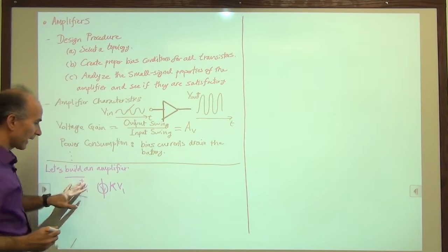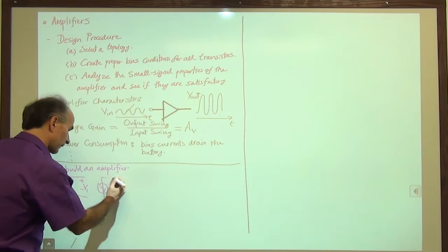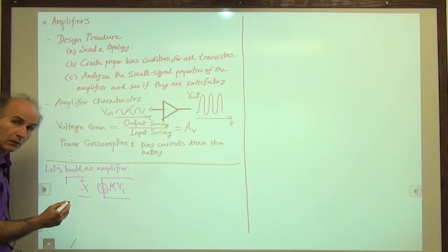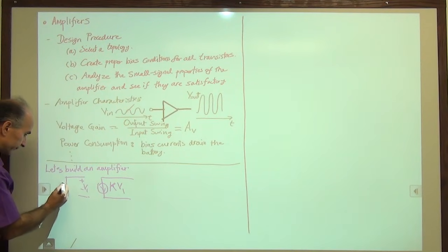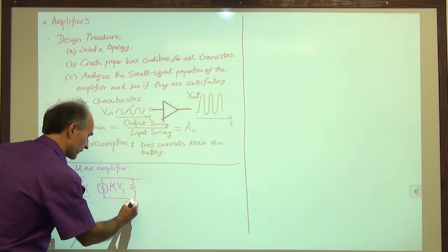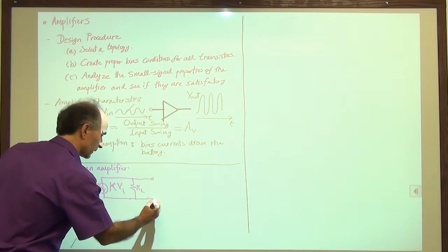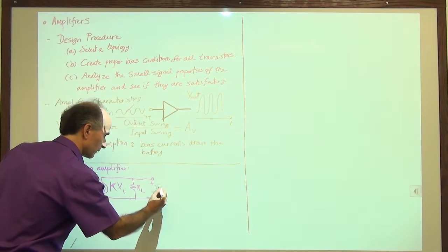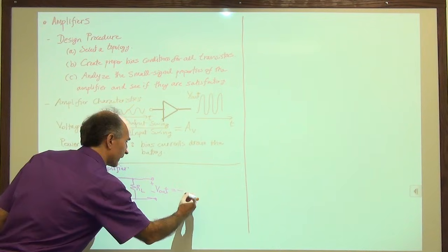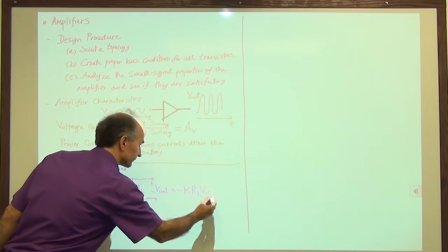We said if we buy a voltage-dependent current source and we connect this to our signal, let's say our microphone, and then we let this current flow through a resistor, RL, we generate a voltage, V out,